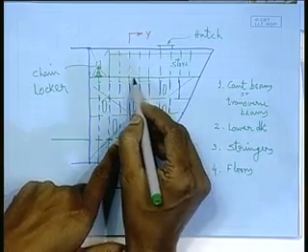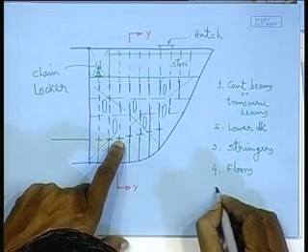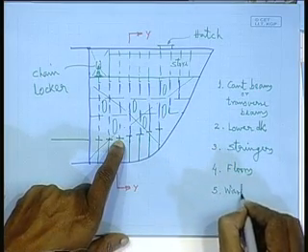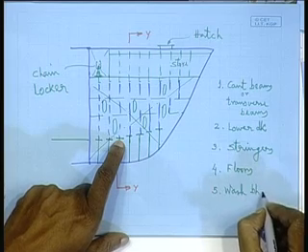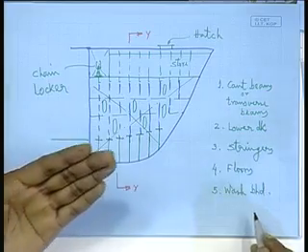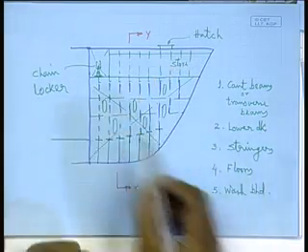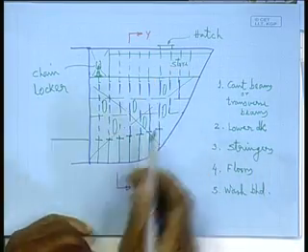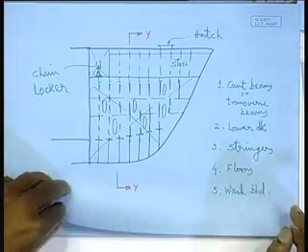Instead of only a center girder of depth equal to that of the double bottom, I am providing a full height wash bulkhead. It's as if the center girder is going up and becoming full height. What is the full height? From the floor to the lower deck. So I am providing one wash bulkhead at the center line, which can be referred to as the centerline wash bulkhead. Obviously, when I put the wash bulkhead, it itself has to be strengthened, so it has its stiffeners. With all these, you have made it quite strong.